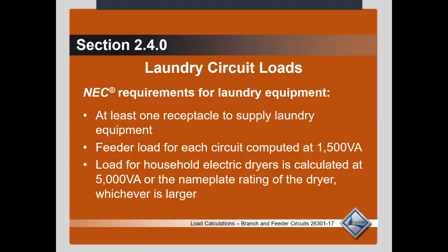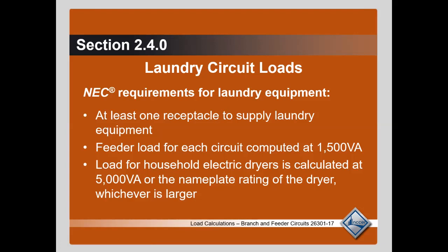Because I haven't built my house yet. I'm trying to build a load calculation off of a building that's not even built yet, right? Because I have to turn this information into the power company. They have to know what size transformer we're going to put outside your house based off of what demand you're going to have. What happens if your demand is larger than the transformer they put out there? It'll blow the transformer. It'll try to use more than it can process, put a strain on your conductors, and then eventually it'll blow that transformer.